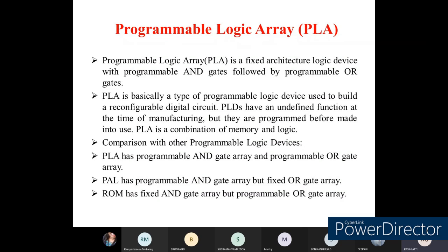After the syntax checking, you go for the synthesis, that is nothing but the RTL schematic. Once the RTL schematic has been generated, you are able to see what components are required to generate this odd parity generator. Once you know the components, you need to see how the communication has to be established between the component entities. The implementation of your circuit diagram will be facilitated by programmable logic arrays.